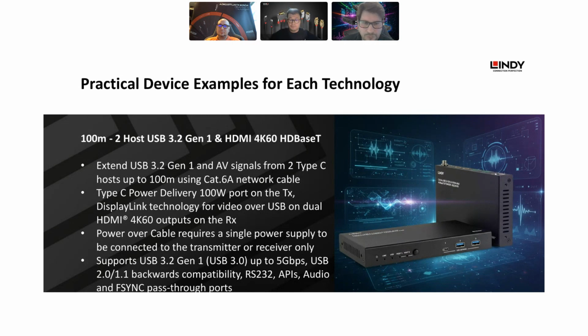This is one of the most recent HDMI standards that we have and that we can offer. This extends HDMI and USB 3.2 Gen 1 signals from 2 Type-C hosts up to 100 meters using a Cat6A Ethernet cable. Type-C power delivery 100 watt port on the transmitter.